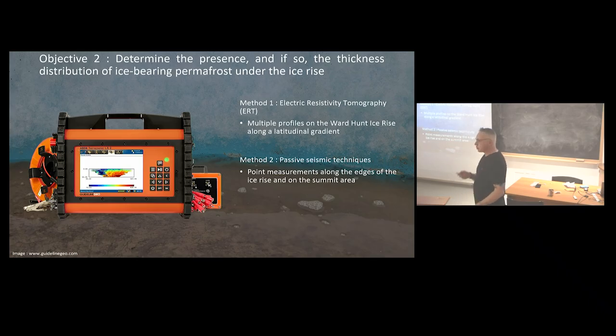So we use electrical resistivity tomography. When we run it, we need to extend for maybe 500 meters, and then we have a little metallic pole at every 2 meters where we put the electrodes, and we send the electric signal, and then we can reach about 70 to 80 meters depth.